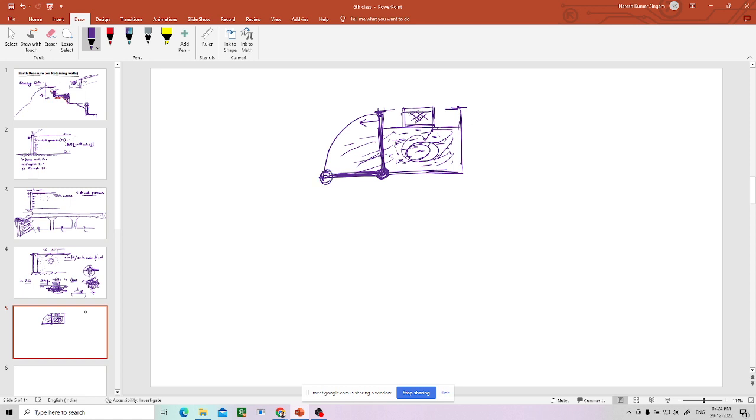You may not need this much movement, 90 degrees. Even by 2 or 3 degrees, this would have already failed. This collapsed. That means the shear stress has reached the shear strength of the soil along one plane, any plane. So that is the thing.